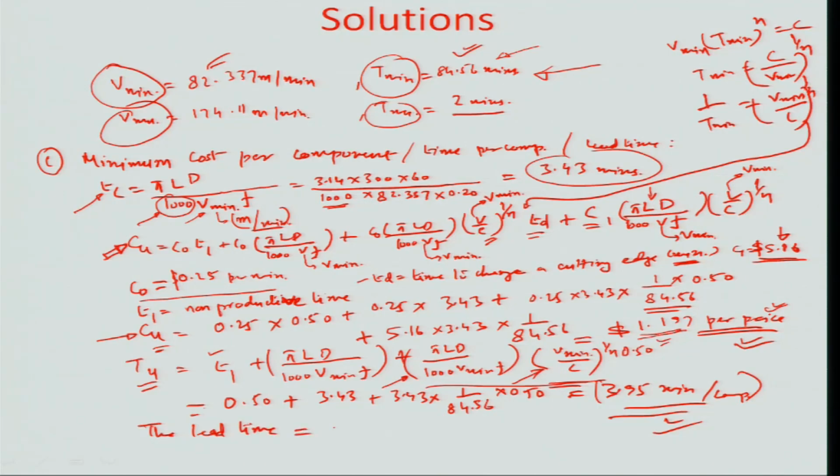So the lead time, as you know, involves the major setup time and then also reflects the time per component times the batch size here. The Q is 500, the batch size we are using is 500. Assume the setup time to be negligible because it's not mentioned in the question. So we have per component 3.95 minutes times 500 as the total lead time for this whole batch to get processed.